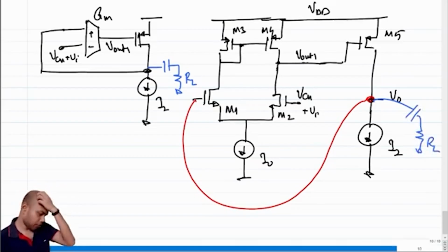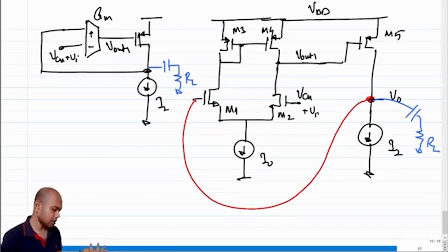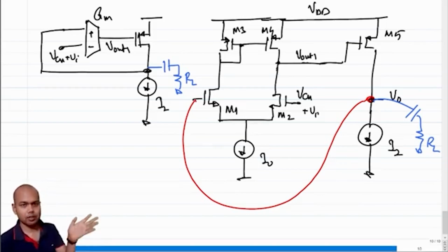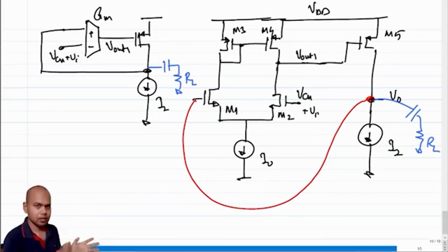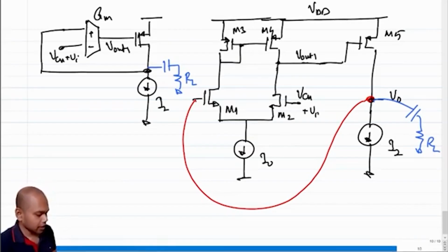Okay. So if we didn't want a unity gain configuration, what would we have done? We would again have put an R by (K minus 1)R and R ratio, taken the feedback part and fed it back, right? That's what we would have done, but in this case the configuration is that of unity gain, right?